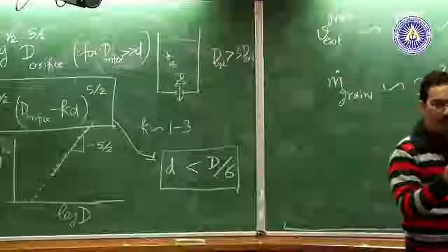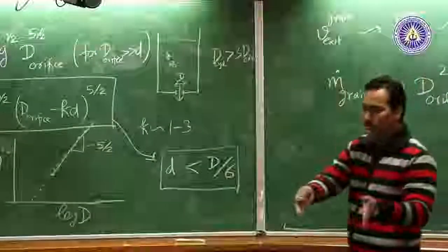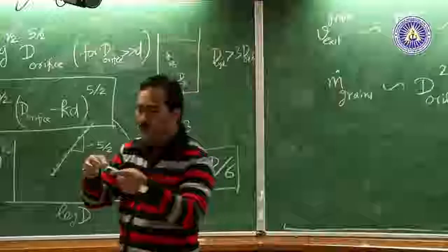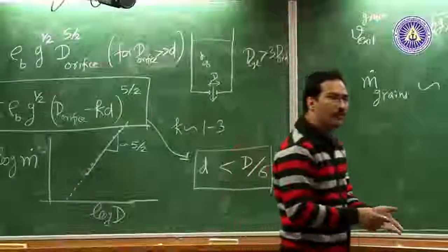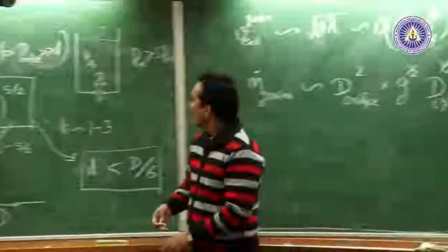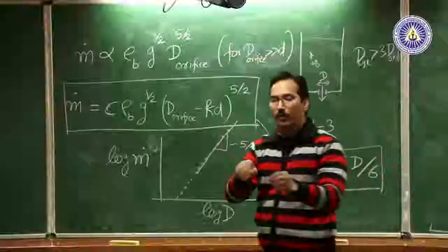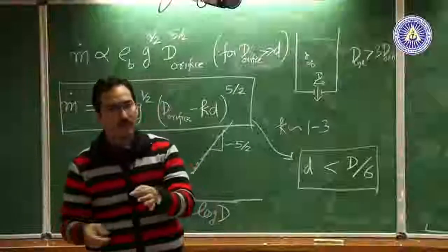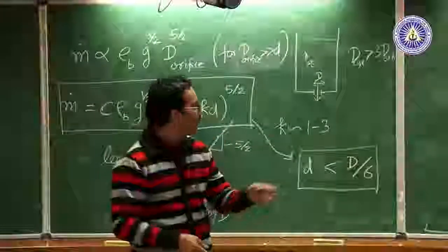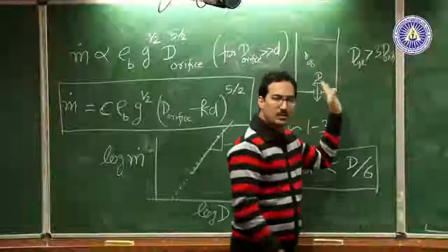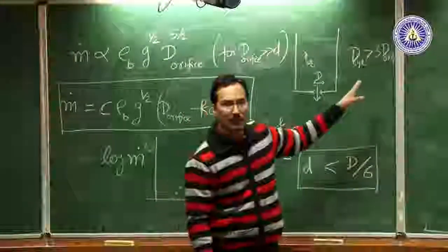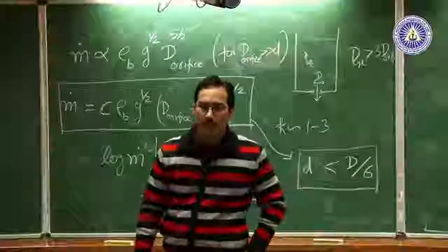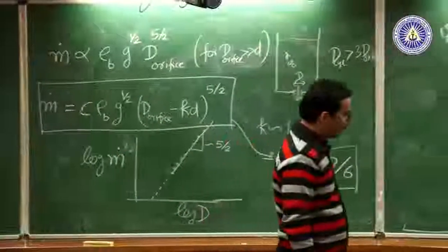If your orifice is not really very close, the extreme case, you imagine the entire cylinder bottom is open, then it will of course fall under the influence of gravity. There is nothing that you are going to observe. So typically if your orifice diameter is a factor 1/3 of the cylinder diameter, then it doesn't really make a difference, and this number is not sacrosanct. Even if you go a bit smaller, you're not really going to see much of a difference. So that's what was Beverloo's observation.